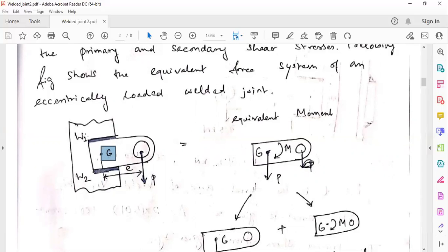It's like you just take the half of, say, suppose this is the total length of your welding. So the middle of that will be the length of Z from this edge, and from the top, the half of the width will be Z. So G is your center of gravity for the welded part, not for the entire part. Once you look at this Z, from the point of application of force to this center of gravity of the weld, that distance is called eccentricity.